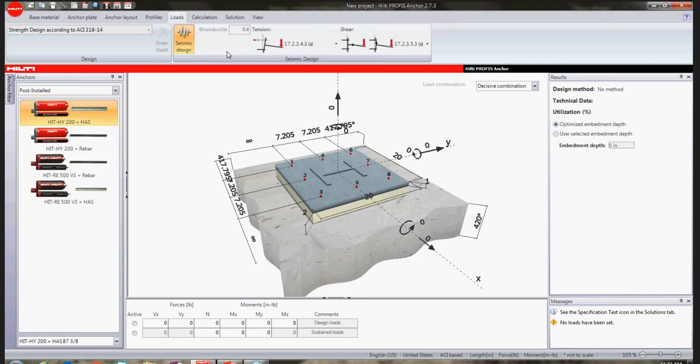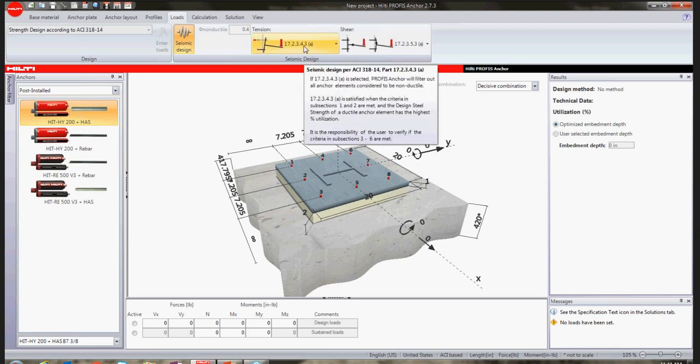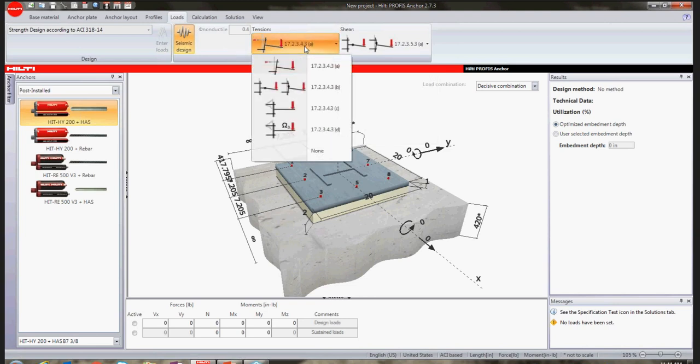And here you can see that we are okay on the tension and shear utilization at 45%. So zooming out, the remainder of the report is going to be some installation data, such as installation torque, what to expect with the product that you selected, as well as geometries of the anchor plate that was used.